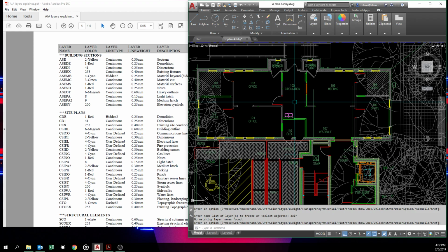Purge gets rid of extra items in a drawing. You're probably familiar with it. There's usually a purge in a number of different software. Like SketchUp, for instance, has Purge. And we'll talk about that in another lecture. Anyhow, there are ways of getting rid of all the extra stuff if you ever need to. So if you input these, put them in that acad.dwt, and you find later they're annoying you, when you open a file with new, you can just hit Purge and get rid of what you don't want to use that day. But all right, I'll hush up. Thank you very much.